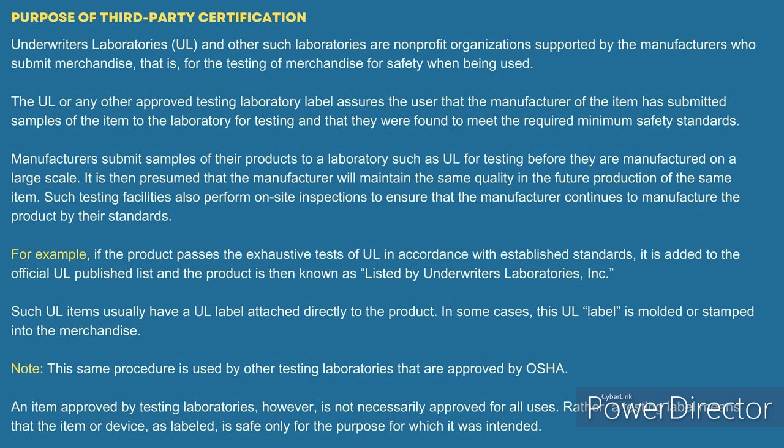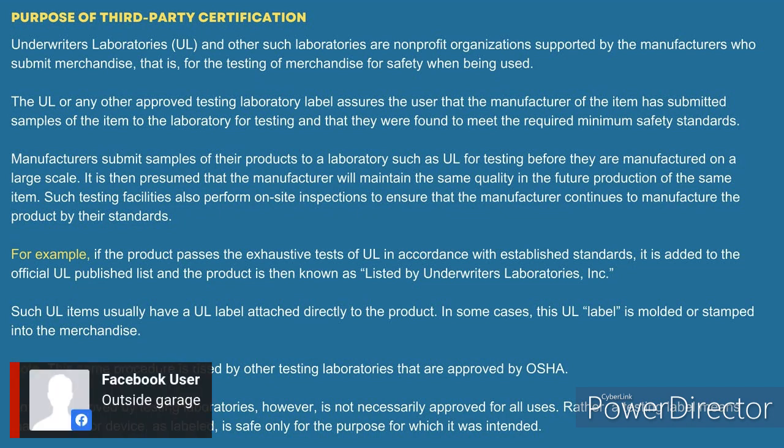First of all, I don't know why you would put it right inside the door there in the foyer. I guess if you had a round driveway, he's saying, coming up in front of the house, outside the garage, but then that would be what they say is covered under 210.8(F) for 2023, expanded areas.